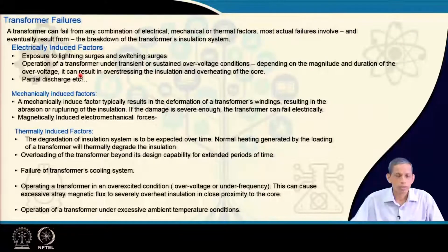Mechanically induced factors: any mechanical problem may lead to winding deformation, leading to rupturing of the insulation. If the damage is severe enough, the transformer will fail electrically.